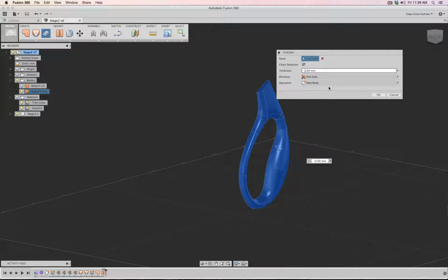So what I'm trying to see is how far can I push the surface to the inside. If I can get it 2 millimeters inside, then that's terrific. If only I can get it 1 millimeter inside, then that's okay as well. Because then I would be able to use a direction and say both sides 1 millimeter, so I end up with 2 millimeter, just grew my part by a millimeter.